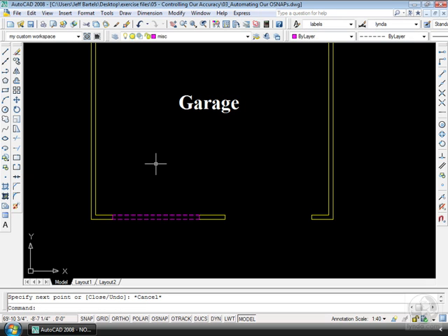Now, that did work, but it wasn't the nicest way to work in the world. I don't like spanning my entire monitor to grab those object snaps. Let's look at a way that we can automate the object snap process. I can do that by setting my OSnap mode. If I left-click to turn this on, that's great, I turned it on. Let's find out what we just turned on. I'm going to right-click on this button and select Settings.